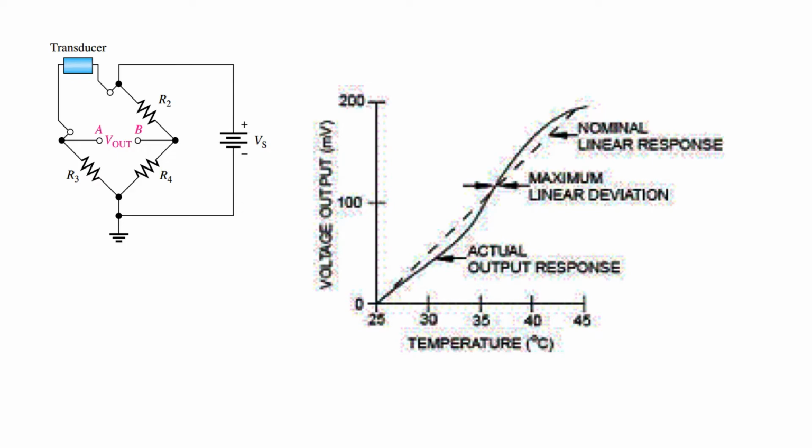By instead measuring the difference in voltage across two voltage dividers, the internal resistance of the thermistor would play no role in the measurement. What the voltmeter sees is zero resistance across junctions A and B. It sees zero resistance, ideally, because there's no voltage across the two junctions.